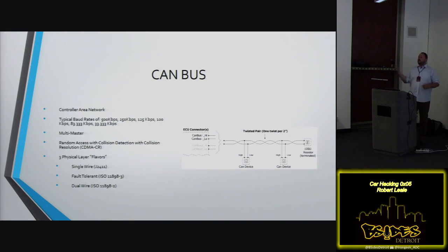And because of that, you have to shorthand a lot of the information, right? Everything needs to be shorthanded. You're given 8 bytes to tell everything you need to say about the status of this particular switch, or this motor, or this. And really, you have 8 bytes, that's 64 bits. If you can put it in 1 bit, put it in 1 bit. If you push the down button on that switch and you can fit it in 1 bit, or if you open the driver door and you can fit it in 1 bit, put it in 1 bit. Because we have 4 doors, plus the hatch, plus the hood. Let's put them all into 1 bit each. And so because of that, everything is really small messages, really quick, simple, and very, very efficient at the end of the day.